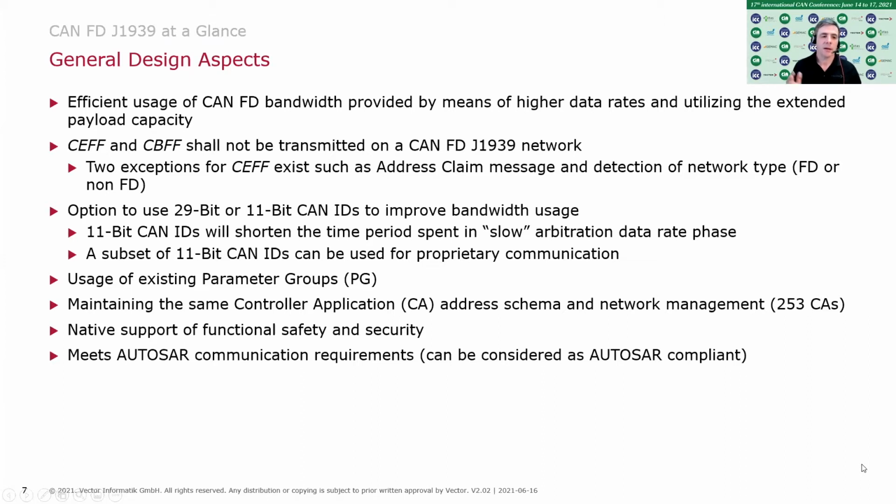But mainly the classic extended frame format and the classic basic frame format shall not be used anymore, because we will learn later about the technical reason behind this. This is an aspect that comes into play if you're dealing a lot with proprietary messages.